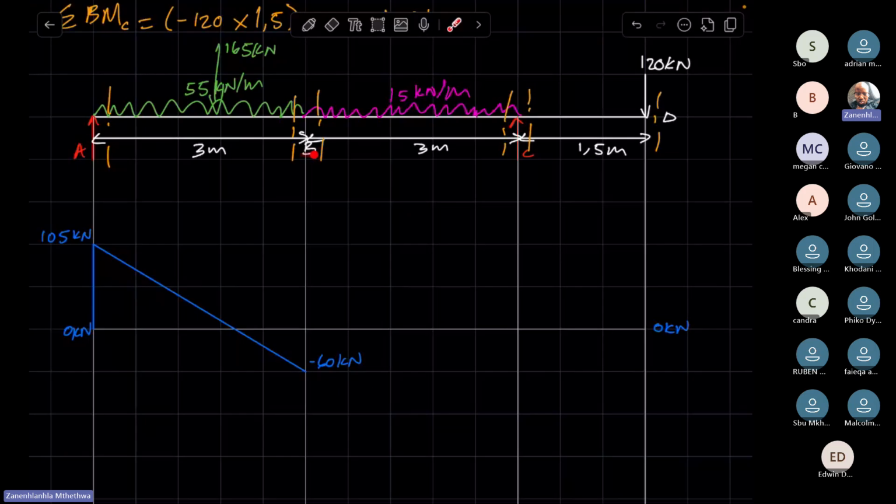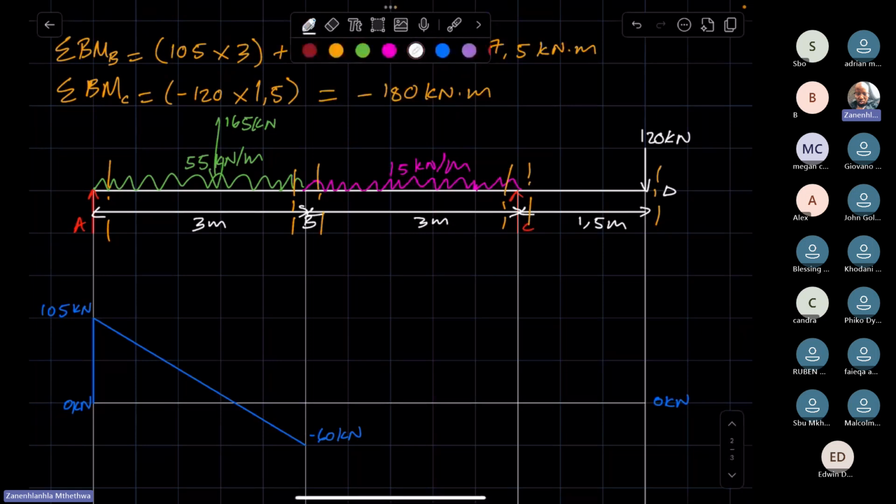Right, so because there aren't any forces to consider between the two sections, you leave this one exactly as it is, where it is. It would be a different story if we had a point load at that point. If we had a point load, then that's the point load we'd consider. Or if you had a reaction at that point, then that is what we would consider. But saying that you have nothing means you have considered all forces on the left of point B.